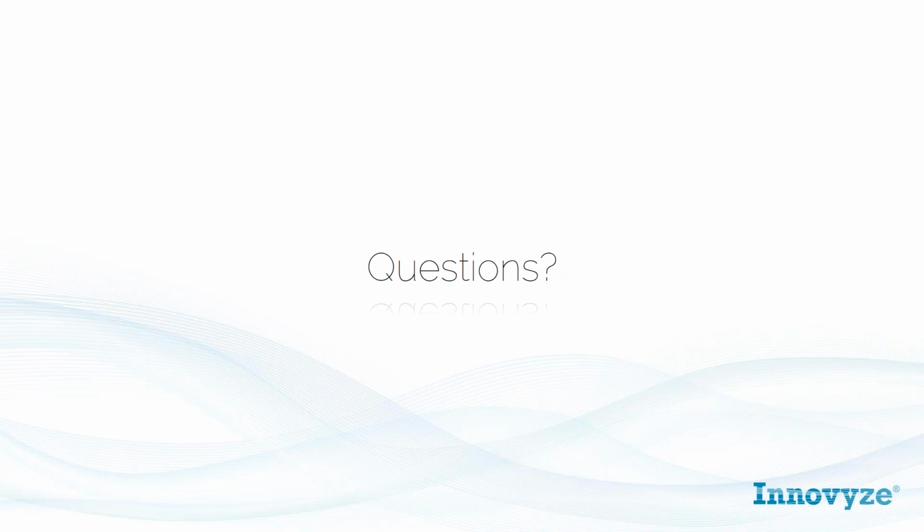I've got two quick questions here about the groundwater infiltration module. The first question is, is it available in InfoWorks ICM? The short answer is yes. Just go to the help file and read up on the theory behind the GIM. The help file is incredibly extensive, especially in the theory around the GIM. It's available in your InfoWorks ICM SE license, and you'll find it in a tab within the subcatchment grid view in InfoWorks ICM.